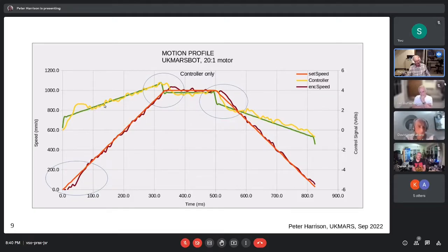And then finally, it starts to kind of get things right. And then it comes to the point where it's got to stop accelerating and travel at constant speed. And now you can see that it overshoots, because you can't suddenly hit the brakes and get the speed just dead right. The controller overshoots, compensates, comes back and starts to converge on a nice steady value.